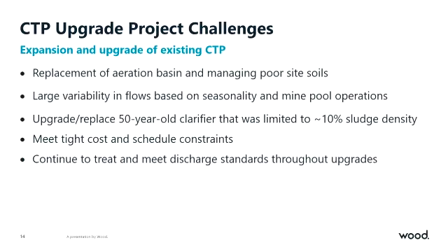It couldn't manage sludge density much greater than 10%. And again, we had to get above 25%. So we had to find a way to integrate that into a new process to be able to meet that sludge density objective. We had very tight cost and schedule constraints, which involved actually operating the contract with the Army Corps of Engineers as a design build contract.